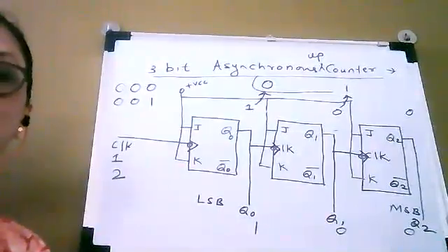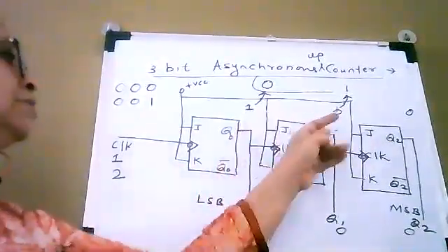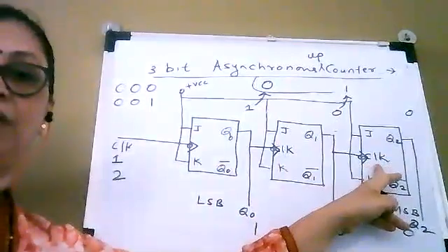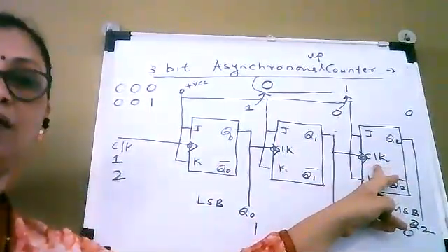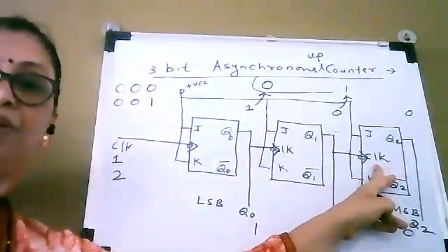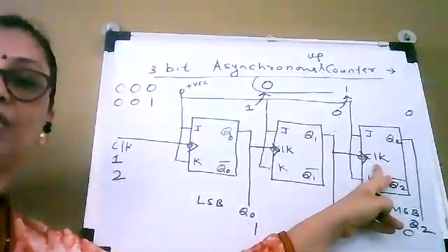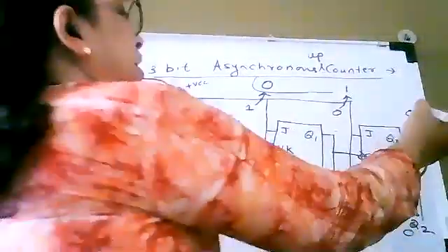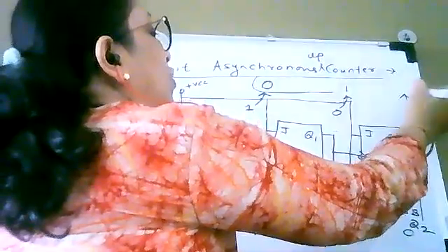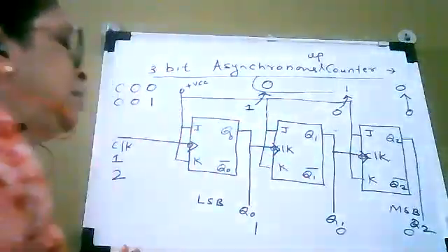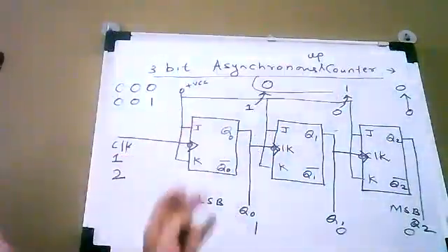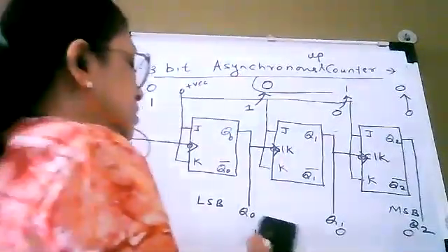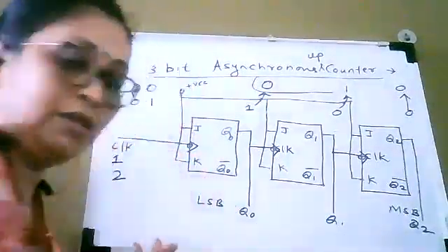So this is a rising edge of the clock, and this is applied to flip-flop number 3. As we are applying a rising edge to flip-flop number 3, it will not be activated. It will not change the state. It will remain the same. So the output of flip-flop number 3 will remain the same. Now we are getting the new state, and this new state will be,